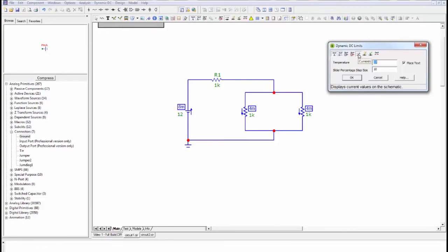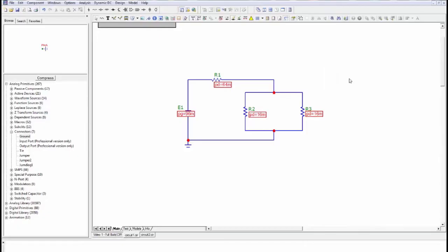Okay, if I move over and turn the current off so I don't clutter the diagram, again move to the right, and this little bolt of lightning on there is for powers, so click on that and it's actually giving me the powers in the circuit. So PD, power dissipation, equals 64 milliwatts in R1. If I want to move these things around, I can do. First thing I need to do is get rid of the dialog box which was active, so now I'm able to move the powers around, which is useful for assignments. Okay, you can move these anywhere you want,